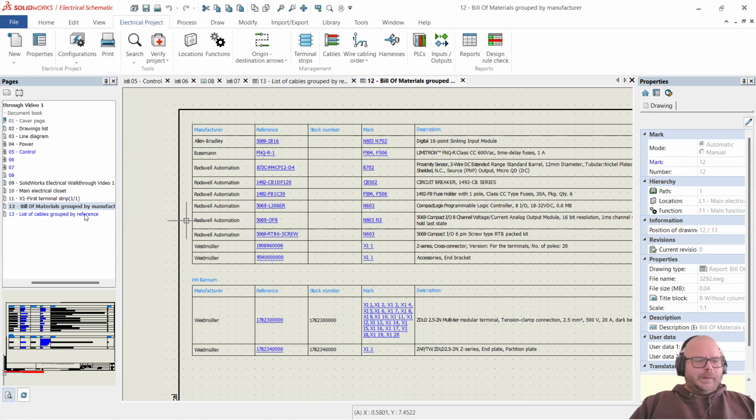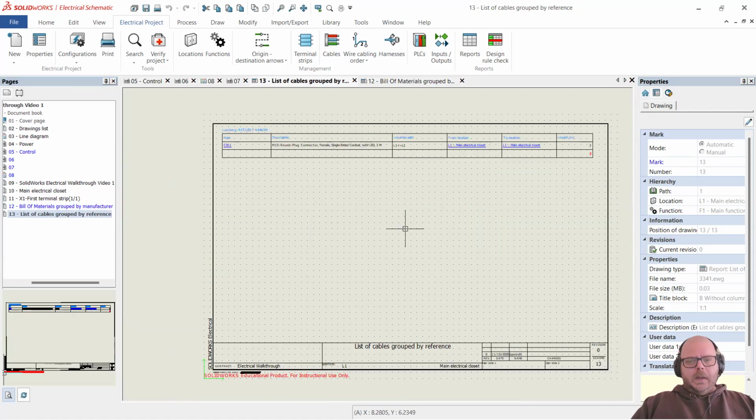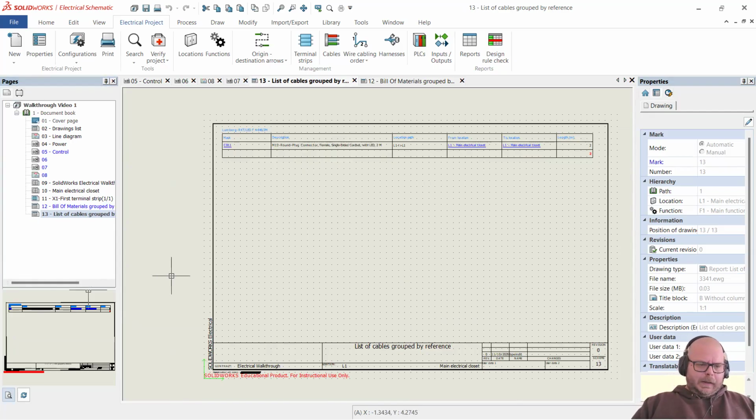We need a separate list of cables. We need that to sort of complete our ordering, because we know, intuitively, this is a part of a bill of materials. It's just that we have to get the software to give us what we need to make it complete. So that is cables. They can get way more complicated, but it's all the same principles. We define the part number, give it all the information we can. We define the cores. And then we just associate those cores with wires that we have already drawn, which is kind of simple.